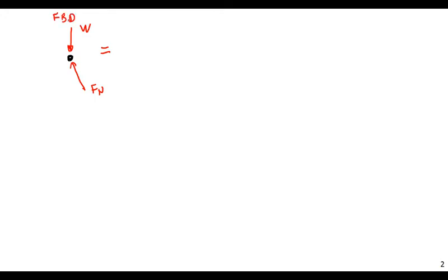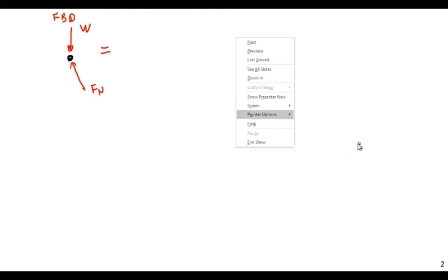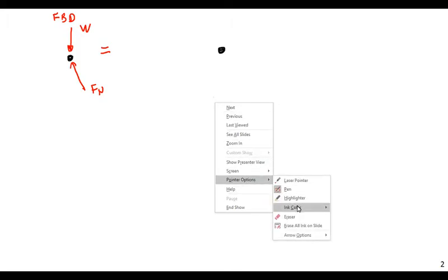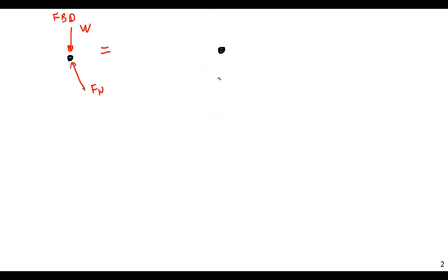But what do we have to set this equal to? What are we setting our free body diagrams equal to? Remember what we called those? We called them inertial diagrams, where we show the acceleration that the system produces as an inertial force. So these two vectors must come together to produce the following inertial force, and that's going to be simply M A sub n, which will in this case be equal to a centripetal force.